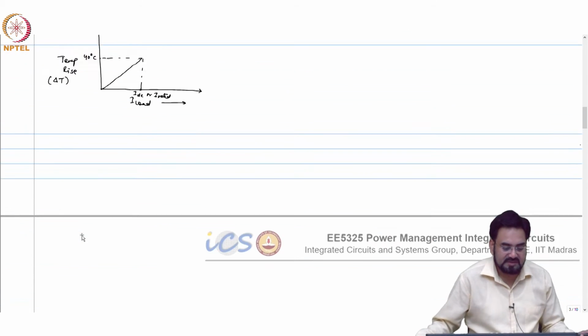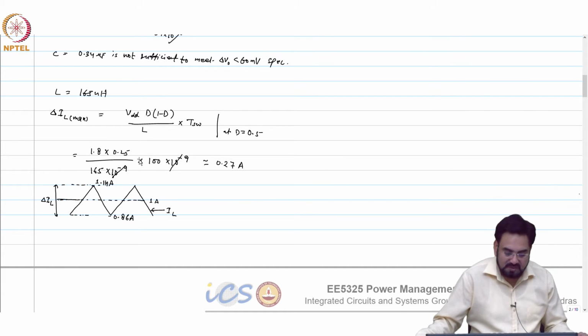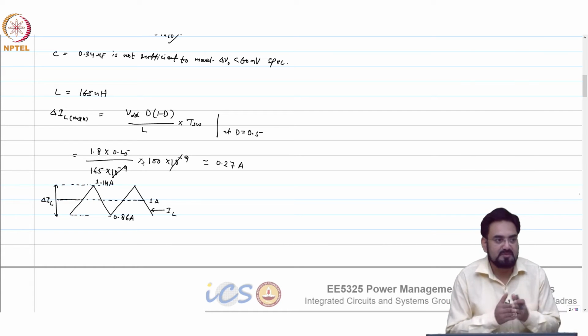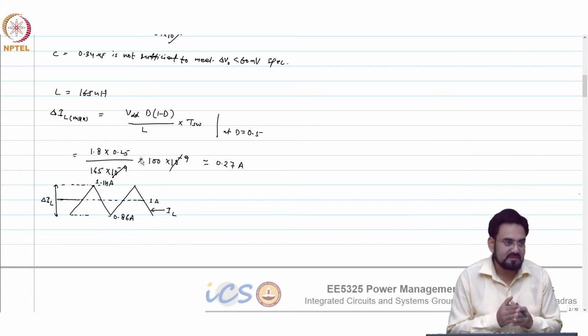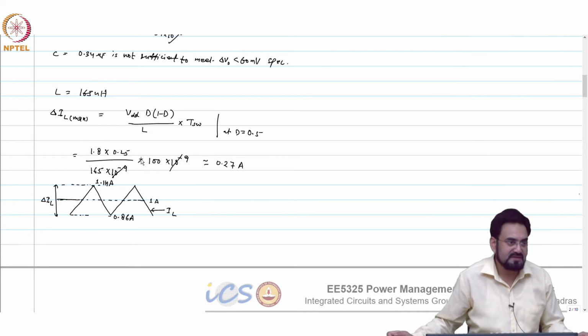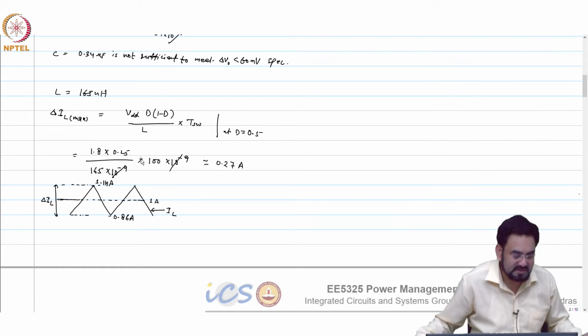So there is something called self resonance in the inductance. Because these inductors will have parasitic caps, if we remember the models we talked about. Based on those parasitic caps, they will have a self resonance. So when you choose an inductor, you have to make sure that the self resonance of this inductor is much higher than your switching frequency. Otherwise, you won't get any value of the inductance. So basically, that inductance is dead when it's resonating.